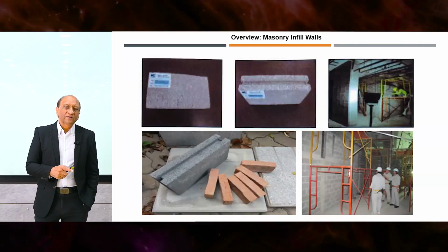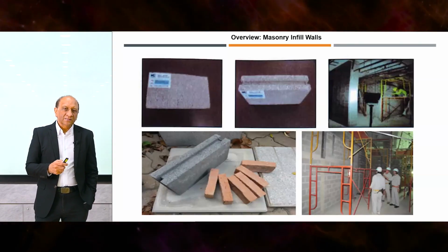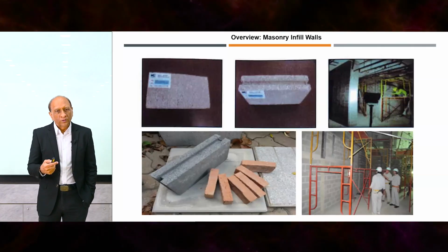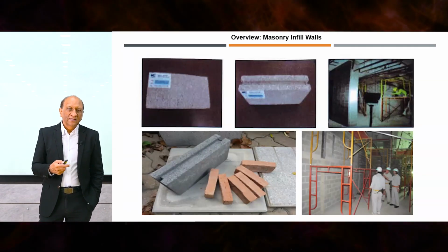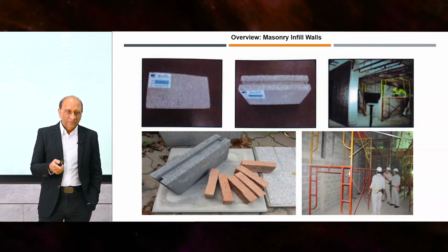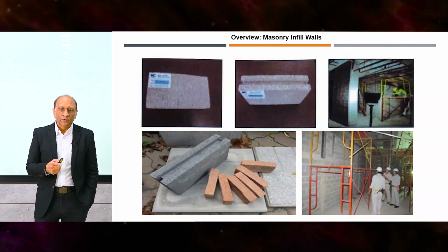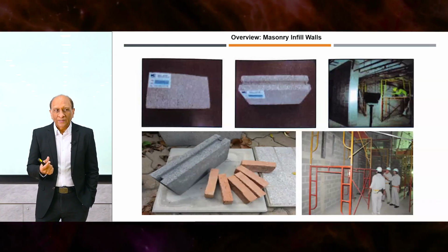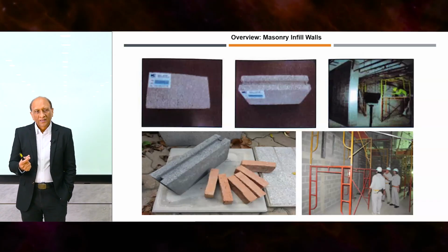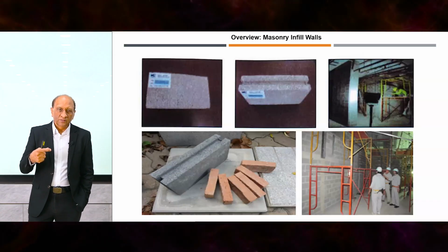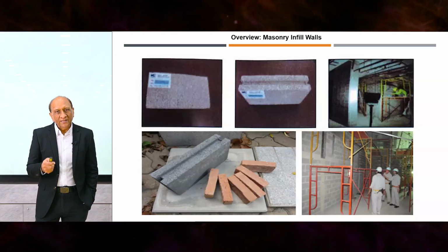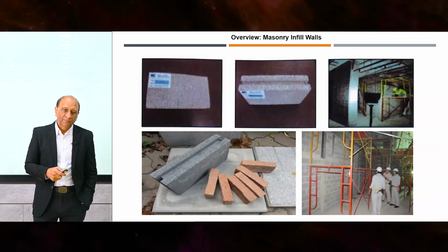Another one is the masonry infill walls. And this is a topic which many engineers choose to ignore, the masonry infill walls in their models. They think it doesn't exist, and they create a bare frame and analyze. But masonry infill, especially in the subcontinent, where they are quite thick, quite large, they have a lot of stiffness, and they have a lot of contribution to the behavior of the structure. Both modal response is affected, linear, nonlinear, both are affected. So incorporating the masonry walls in the model is rather important.